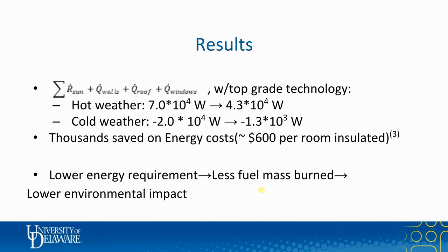Increasing the albedo from 0.2 to 0.65 and the R value from 8 to 32 decreases the energy values by around 30%. As you approach perfect insulation, this means hundreds to thousands saved yearly on energy costs. The impact on the environment, if we consider all homes in the country, would be largely beneficial too.